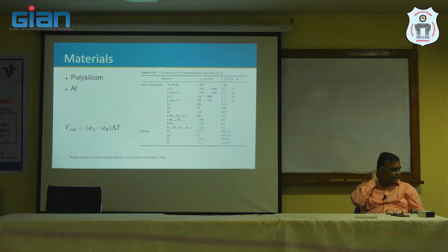So, here is the characteristic of some other materials, and you can immediately see that metals, or at least some of the metals like aluminum or gold, have very low Seebeck coefficient. So, if I already choose polysilicon with around 190, or if I can dope it nicely, I can also get slightly higher. The beauty of some of these metals is that aluminum or gold is tricky to introduce in a CMOS foundry, because gold ions start diffusing in silicon and start changing the transistor properties.